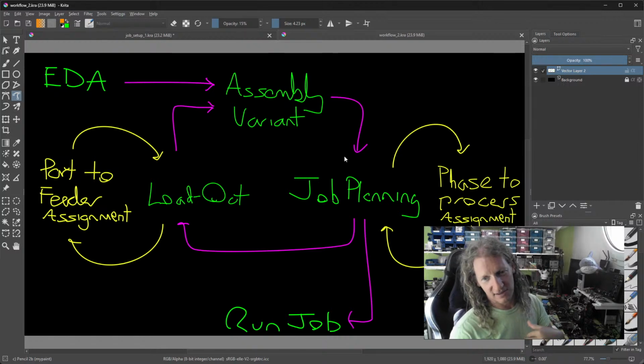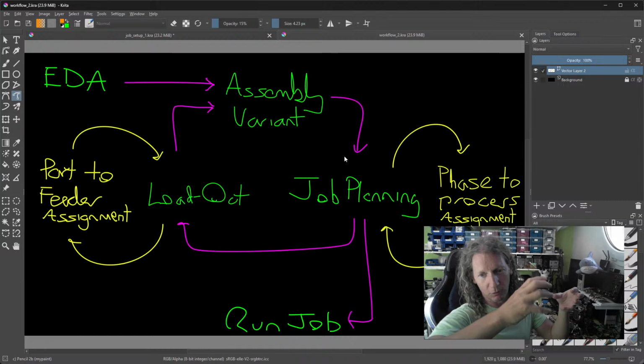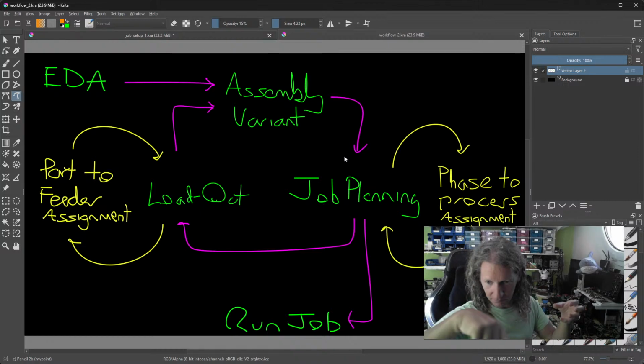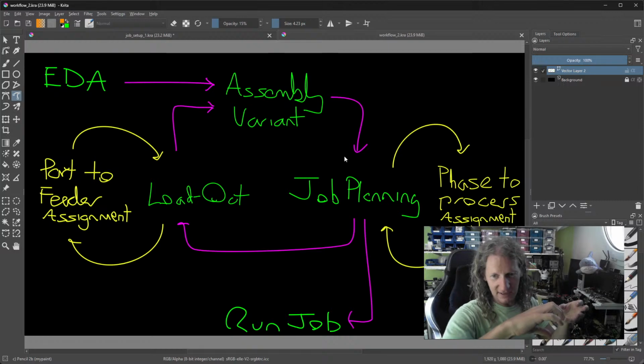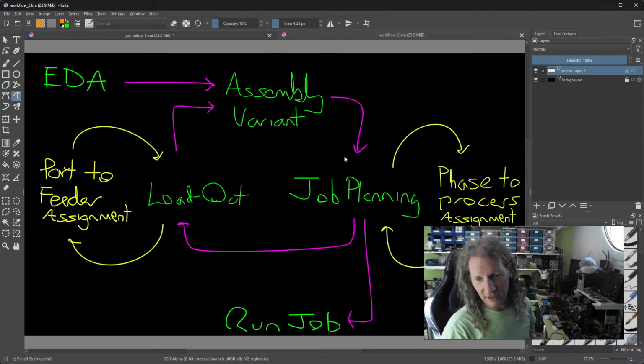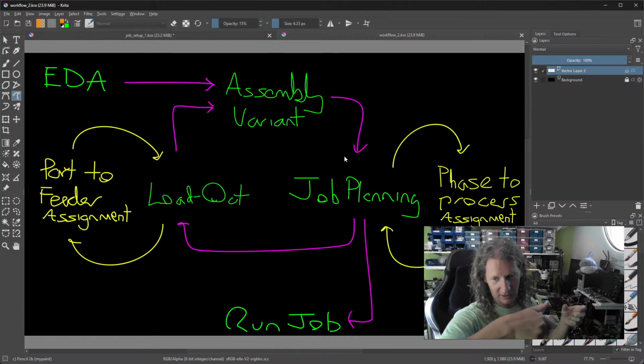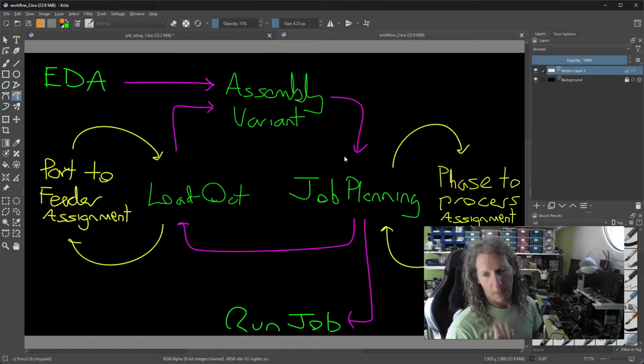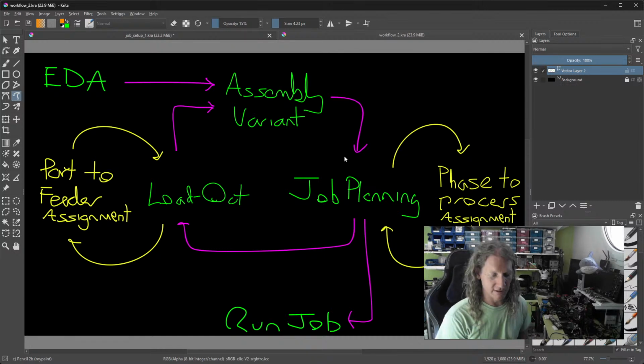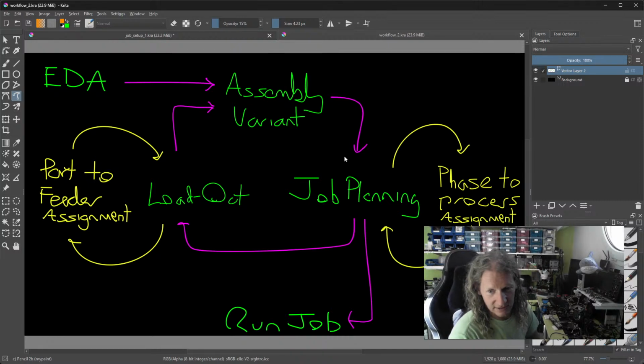So on some machines there's tricks that you can do, which is like put a fold in the tape before it gets pulled round, so that the glue is facing away from the place where it collects on or gets stuck on and things like this. But setting up those feeders and changing feeders where you've got this flip on it is even more of a faff. So that's another high cost of change. So you want to avoid changing the feeders in your machine that have a high cost to change, such as ones that are in the middle or ones that require additional steps to set them up. So you've got a cost to changing a feeder, which is interesting.